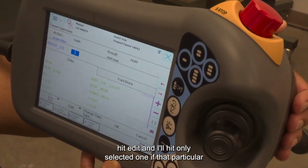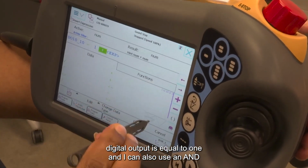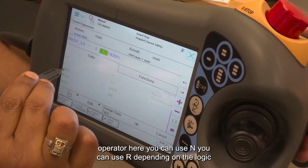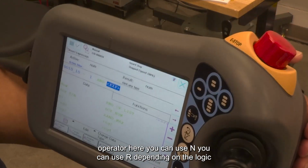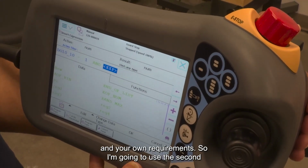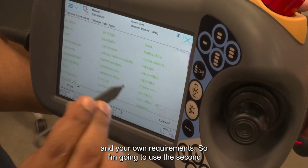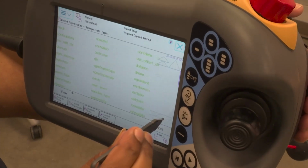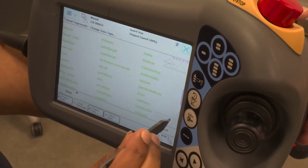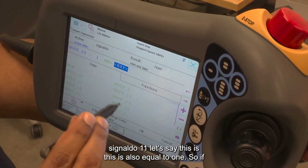If that particular digital output is equal to 1, I can also use an AND operator here. You can use AND, you can use OR, depending on the logic and your own requirements. So, I am going to use the second output, signal DO 11.